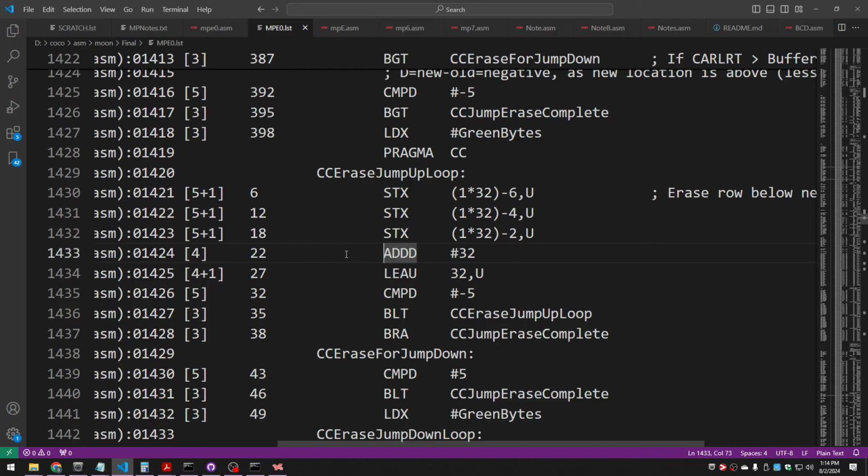If I did that, I would be saving some work. The update of the loop variable, that cost me 4 cycles each iteration. I could just not do that at all. The compare and the branch, that's another 5 plus 3 cycles, gone for each iteration. In fact, all the conditional code that asks, am I jumping, then do this kind of erasing, and if I'm not jumping, then do this other kind of erasing, and check to see whether I've slid or not slid.